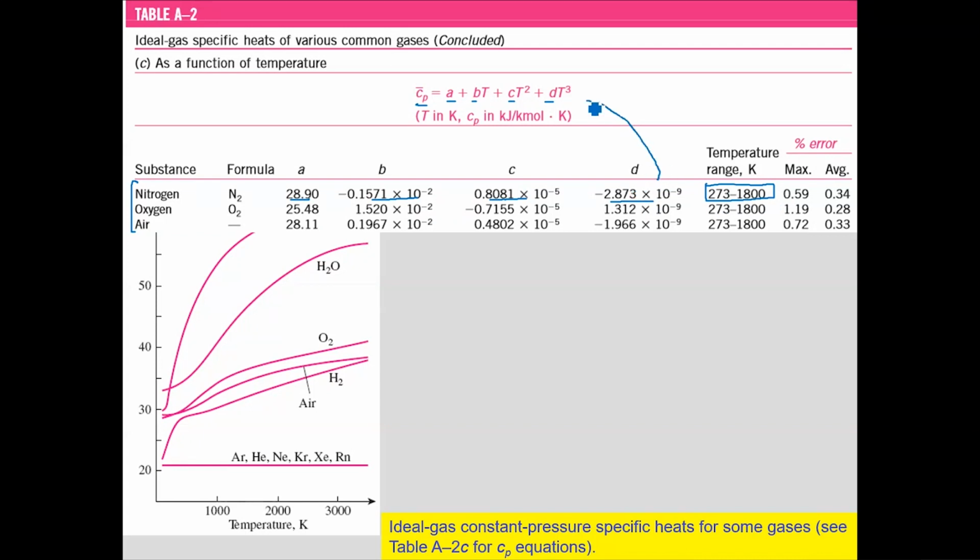If you plug these constants into this equation, you will have essentially an equation between Cp and temperature. So you can plug that relationship of Cp(T) into the equation and integrate with regard to dT from T1 to T2. This would give you delta h for that specific gas between T1 and T2. But the calculation is very hectic. This is one way to find out delta h or delta u, using the exact relationship between Cp and temperature to find the integral of Cp(T) dT.